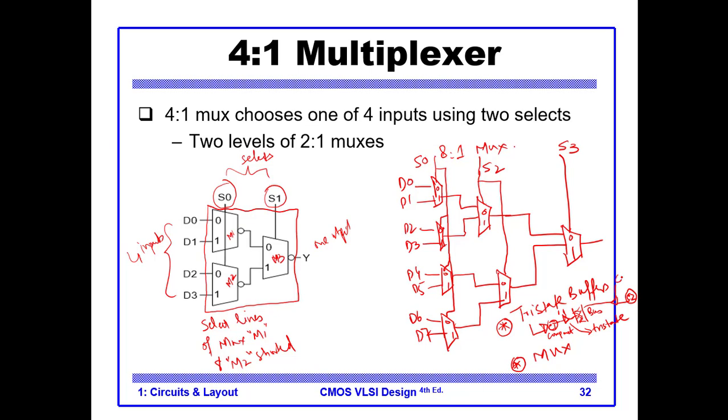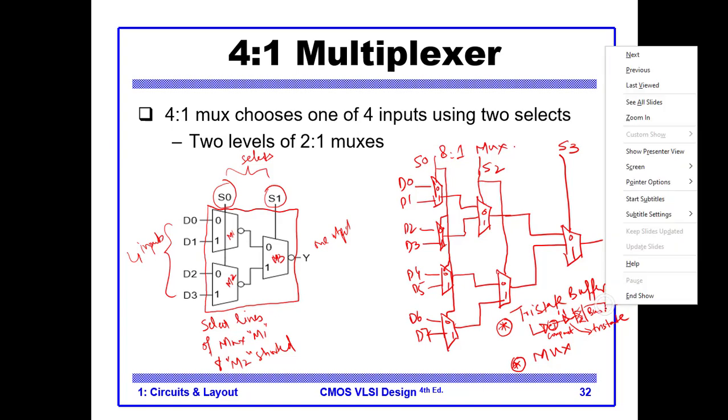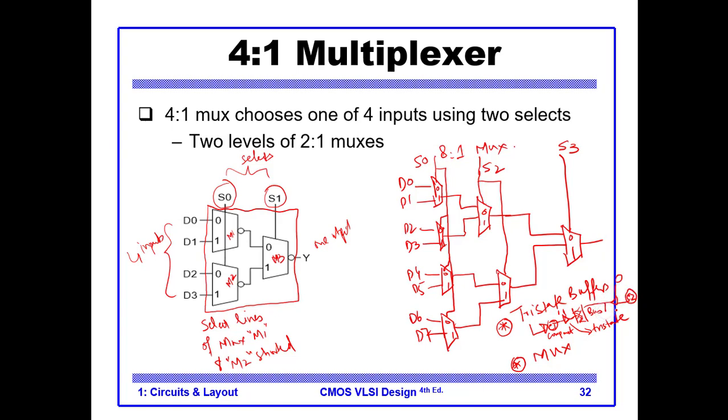At that moment, C2 will disable its connection. So C2 is not putting something on the bus. But if C2 is, for example, the receiver, then we will have another tri-state buffer like this on the receiver side, and this will be enabled.